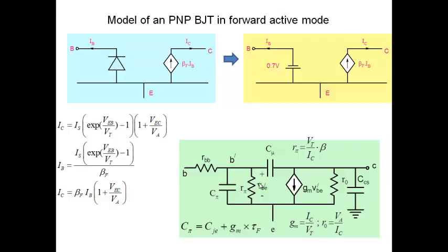In your small signal model, same equation, everything is the same. IC, VA, GM, tau F, everything is the same. Of course, for every transistor, there's a unique set of what is RBB, what is beta, what is VA. Each transistor would have a separate set of these parameters.